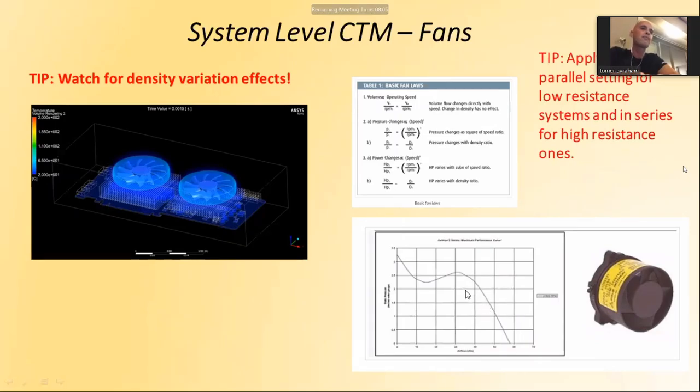So first of all, there's a working zone for the fan. You work only in this zone here, which starts here and ends here if it's free flow. But you wouldn't use this fan for free flow if you probably had a point of operation which needs a lot of inches of water.